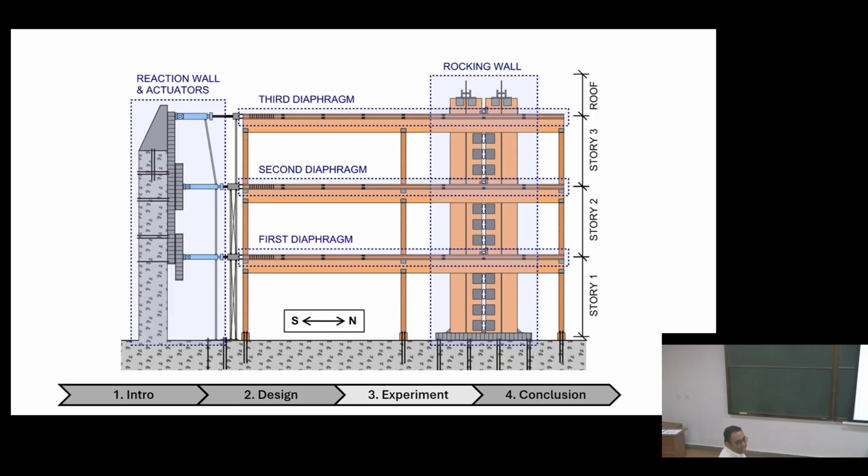Remember, Datta sir showed you a video of the testing here with actuators. And generally, you have your mode shapes, right? You did some eigenvalue calculations. How did your first mode shape look? Did it look something like this? So it's pretty much a linear distribution of your first mode. So that's what we assume, that we'll have a first mode distribution.